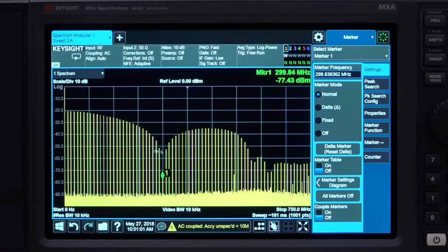Now 500 megahertz is going to sit somewhere around here. So you can see that there is indeed a little bit more frequency content coming out of the instrument beyond 500 megahertz, but it really wouldn't be very useful at that point. So let's go ahead and put a filter in front of this and see what it looks like after that.